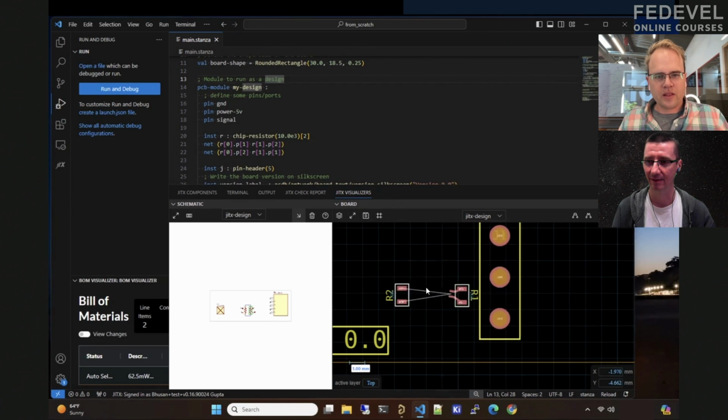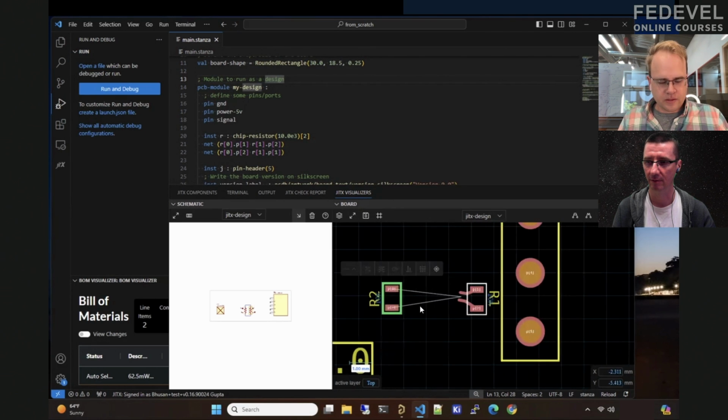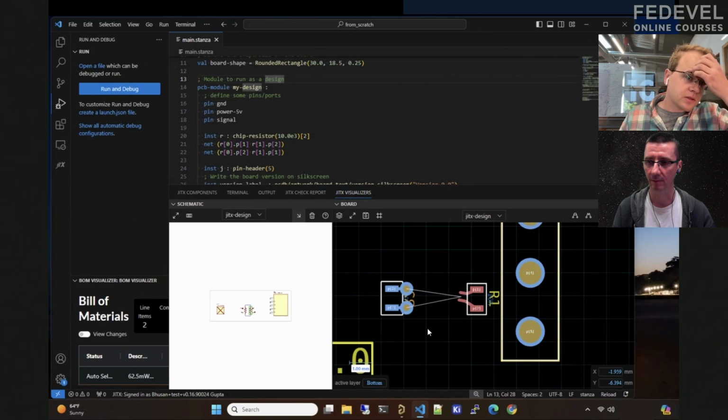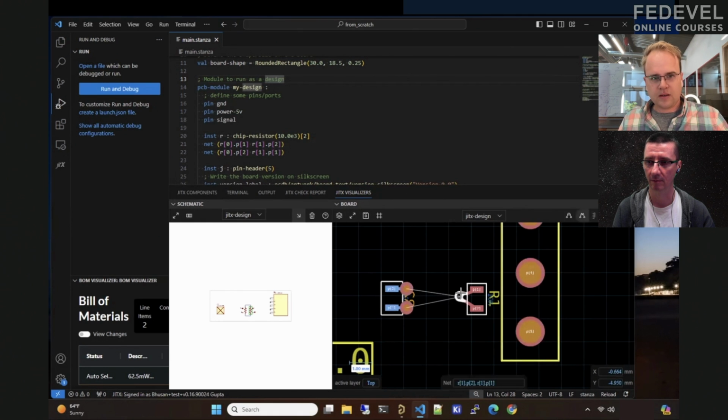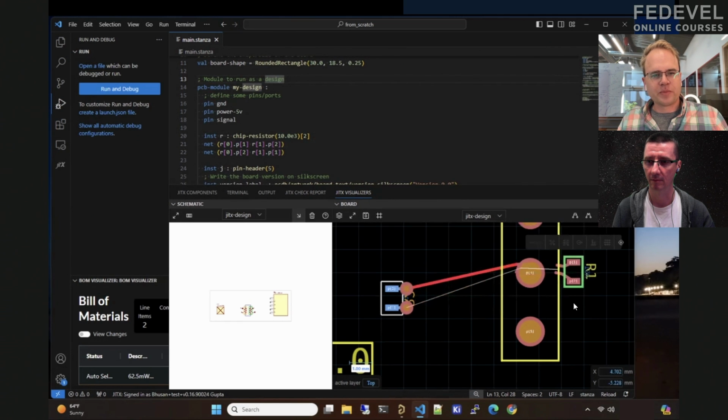Yeah. So I flipped this to the other side of the board. I'd probably get some vias out. Another thing you can do is use the automated via tools to automatically fan out. And then here I would do three like that. And one nice thing is that the differential pairs have the same... Of course, I break it right away.